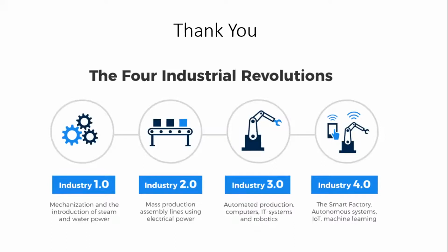Dr. Subbu. Yeah, please proceed. Yeah. Thank you, sir. Good afternoon, Dr. Lakshmi, sir. Sir, it was a very nice talk. I just had a few doubts with regard to the initial presentation. Sir, you said that in general, keyholing is a bad phenomenon in this case. But sir, doesn't keyhole increase the laser absorption due to multiple reflections? And in that case, if you're able to control the porosity, wouldn't that be a better option? Yeah, because we can get a deeper melt pool in this case.